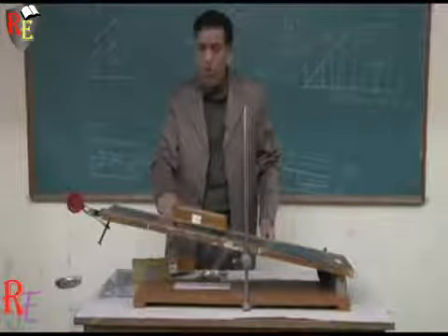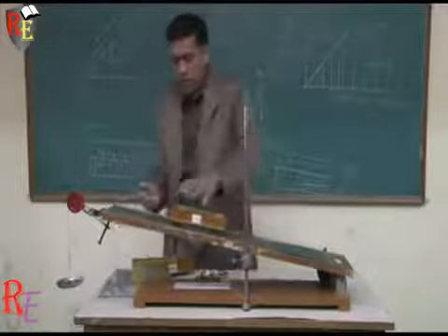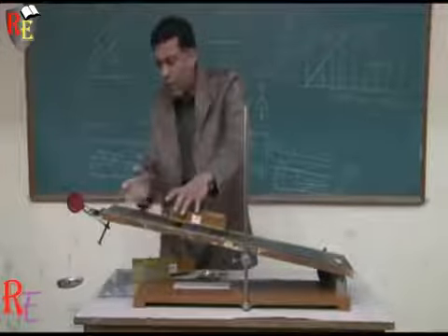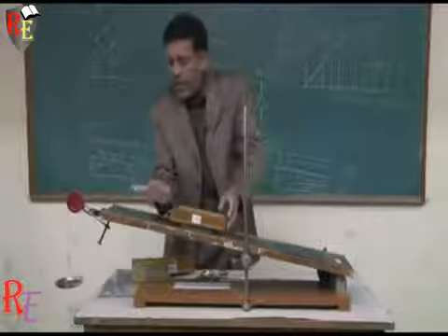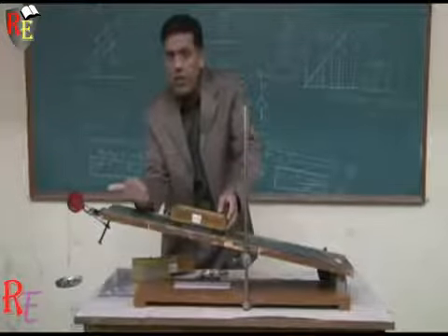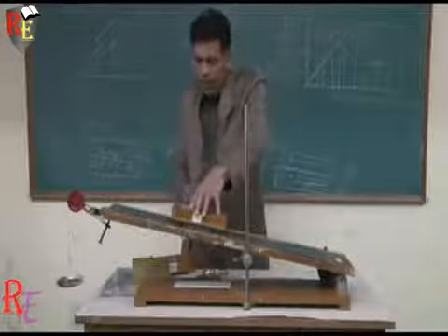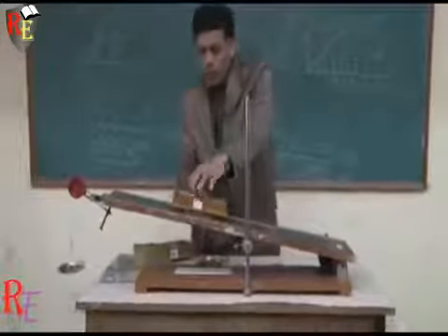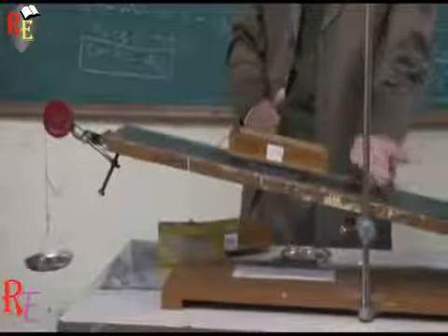is on the verge of the motion, upward motion. And suppose now it is on the verge of the motion. So at this point, the tension in the string is acting upward. Okay. This block has a certain weight W. So its component is acting down the plane and that component is W sin theta.